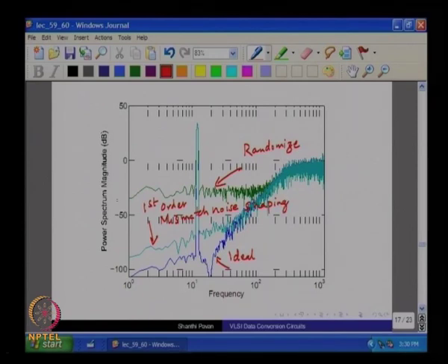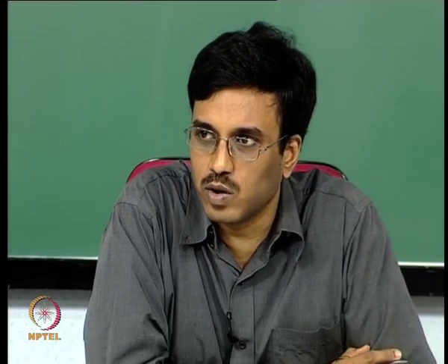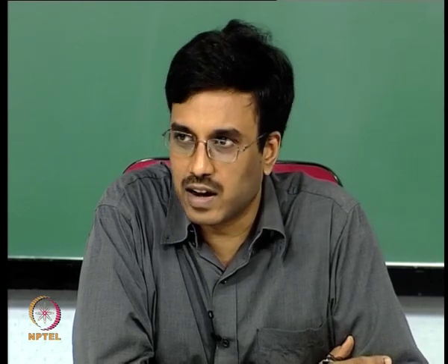Right, and you can see that you have gained significantly, right. If you assume that this is the band edge and most of it is getting contributed here, you can see you have gained a good 40-50 dB, right. And this 5% mismatch happens to be a really bad example as far as mismatch is concerned. I mean, just because you have something which shapes the mismatch noise out does not mean that you can go and deliberately build a lousy DAC, right.